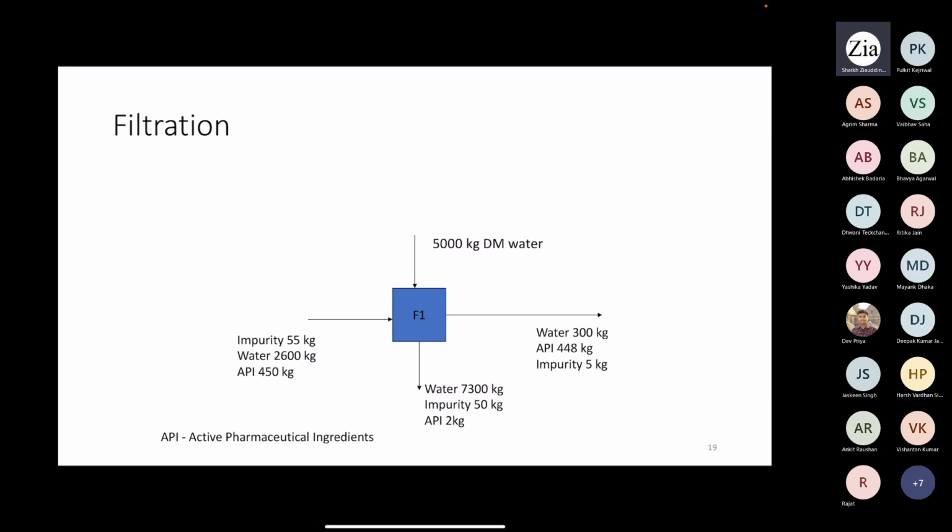Now, when you check each unit, like in upstream or downstream processes, you actually need to do mass balance and energy balance across the unit. Means if you have certain things going into the system and coming out from the system, then you do the balancing and check what kind of product you are getting from that particular unit. That product may not be the final product; it could be an intermediate material for the next process or next reactor.